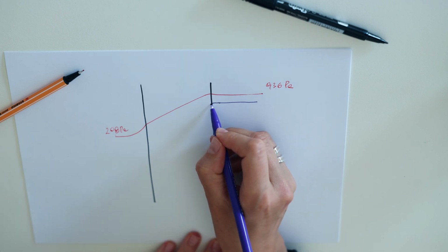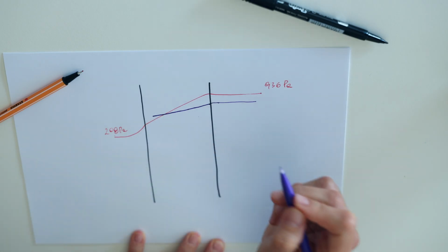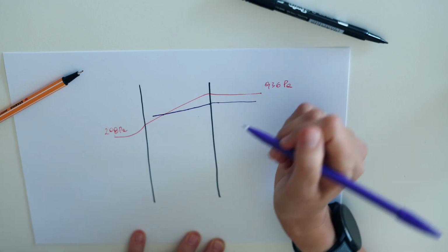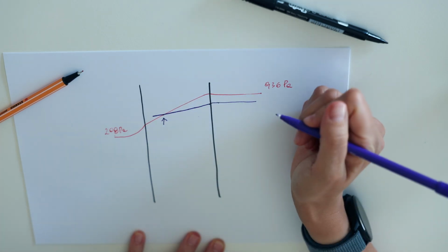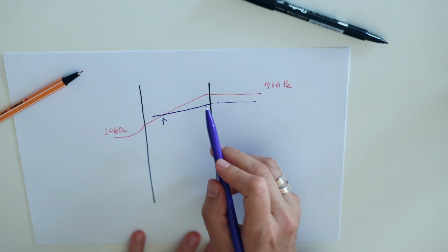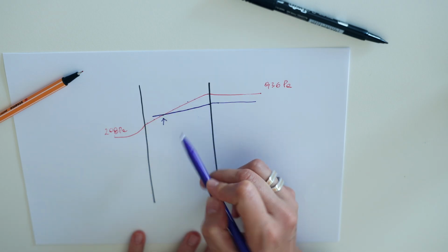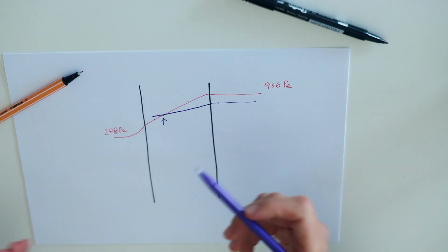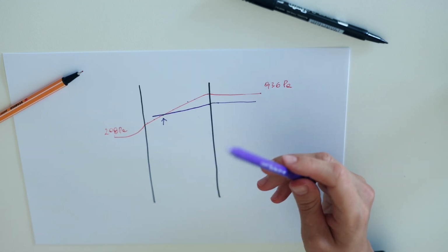And if at some point, when the pressure and the temperature change in the wall, the line of the calculated pressure crosses the maximum saturation pressure line, condensation occurs. And this means not only that we know where it's occurring, because we know for each of these points what is the calculated pressure and the maximum saturation pressure, because we know the temperature, but also how much condensation will occur. With this simple method, we are able to address in simple terms the risk of interstitial condensation.